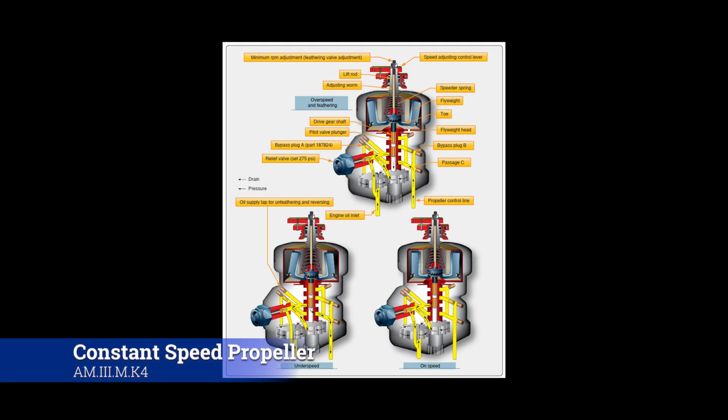they are unbalanced, then bad things end up happening, and that can happen from a variety of different factors weighing in on the aircraft. Well, it suffices to say for right now, you have the tension of the speeder spring that's pushing down on those flyweights. Those flyweights are then controlling the amount of oil that comes into the governor, and then turns around and is going into a hydraulic pump or hydraulic cylinder, which is actually turning the blades one way or